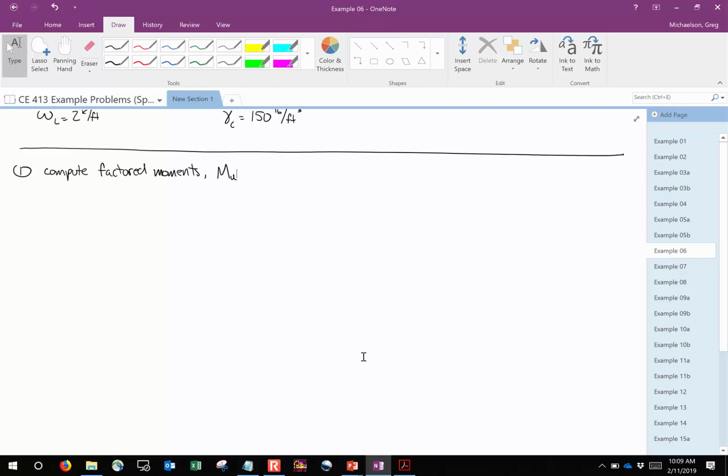Now, does anybody remember if you have a beam, let's say it's B wide, H tall, and so long, how you get the self-weight of that beam? You take the unit weight and you multiply it by what? The area. Exactly right. So ultimately what we're going to be employing is W naught. If you ever see me use the term W sub naught, or W sub 0, that's the original weight. So I use that to refer to the beam self-weight.